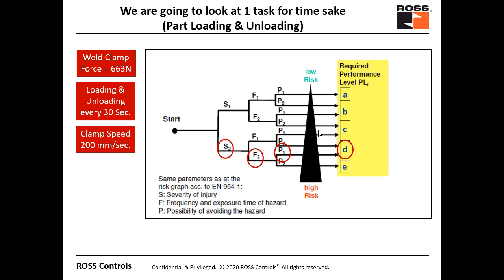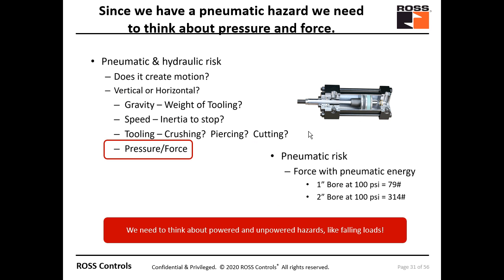Okay? Since this has pneumatics, we need to evaluate that force, okay? So an example would be, I need to look at what the bore is of that cylinder. I need to look at what the tooling looks like on the end. Is that tooling flat, or does it have a sharp point that can pierce me, or has it got a very sharp edge that can cut me? We need to understand that tooling, the speed it moves at.